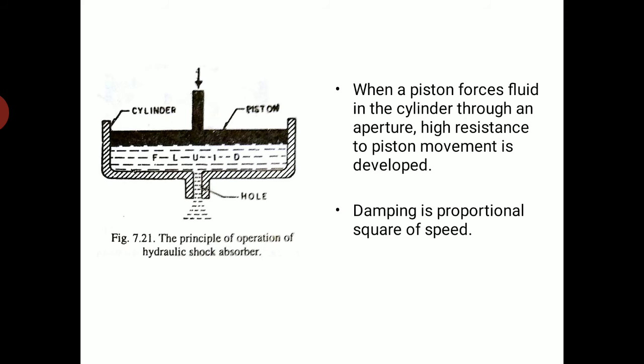If a wheel of a car hits a bump, the spring compresses, then the spring expands after the wheel passes the bump. The expansion of the spring causes the car to be thrown upward, and having over-expanded, the spring shortens again. This action causes the wheel to momentarily leave the road and the car drops down. The action is repeated until the oscillation gradually dies out.